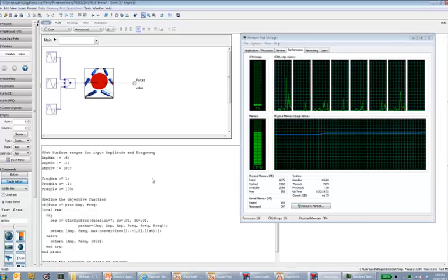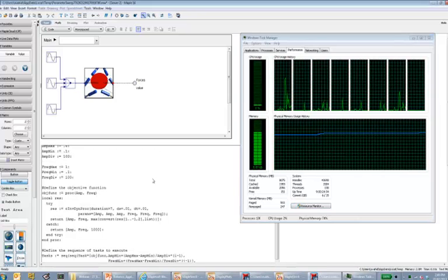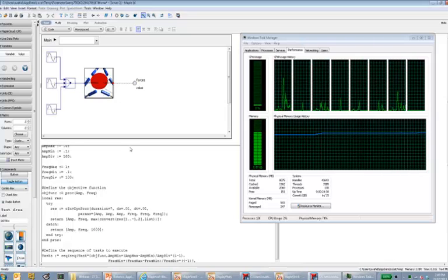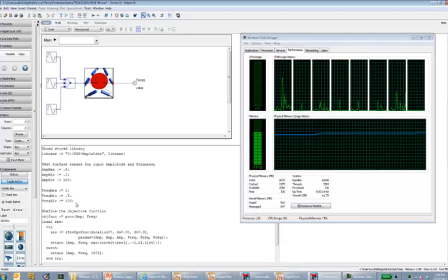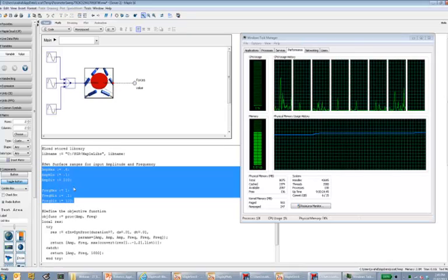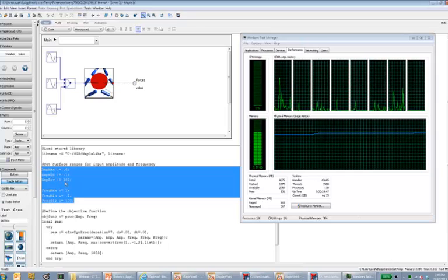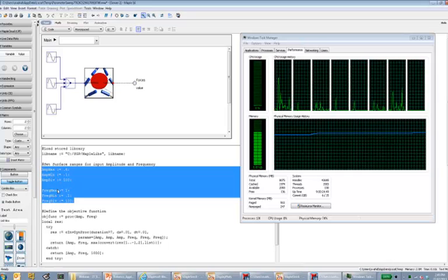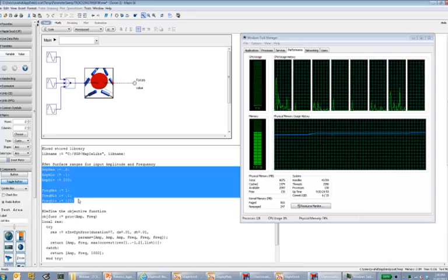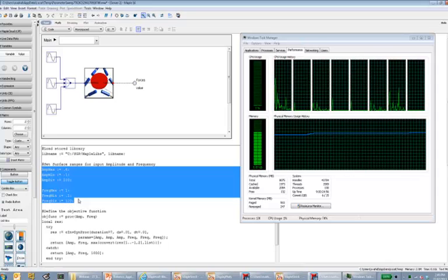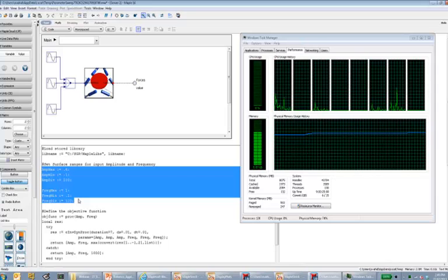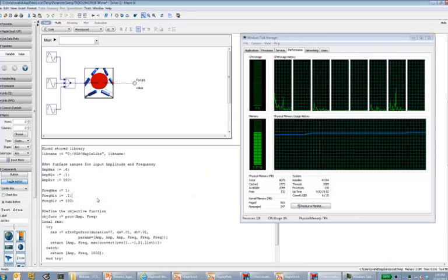What I'm doing right now is getting the entire procedure that solves the inverse dynamic model of a Stewart platform, and going through various trajectories. I'm changing the amplitude in 100 divisions, changing the frequency in 100 divisions, and calculating the maximum force the actuator needs to provide for all of these cases, 10,000 cases of simulation.